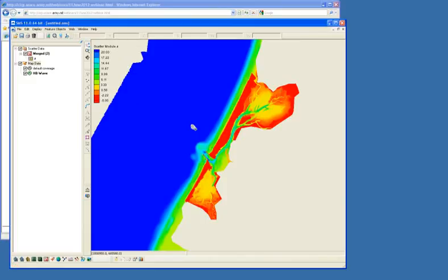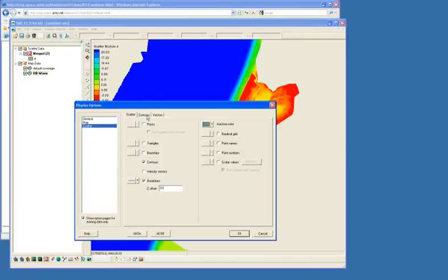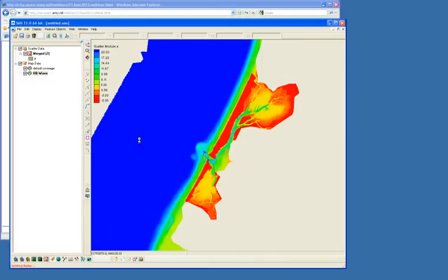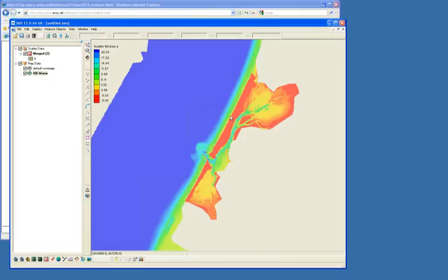So now what we need to do is make sure that the wave coverage is selected. Then we can draw a wave grid frame, kind of like we did for the other. Another thing I'm going to do real quick is go back into display options and turn on some transparency like we've done a couple of times, just so that we can see the grid frame and the refined points without having to look really that hard for them. So let's create the grid frame with the Create Grid Frame tool that's right here.